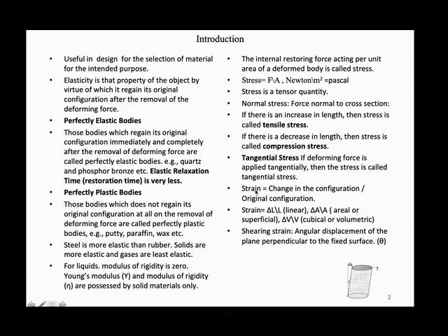So what is strain? Strain is defined as the change in configuration divided by the original configuration. It can be a change of length, a change of area, or a change of volume. If I apply pressure, the volume gets reduced. If I reduce the pressure, volume gets increased. So there is a change in volume, like there is a change in area, a change in length. This is the strain: change in configuration by original. If it is change in length by original length, we call it linear strain. It is areal strain, delta A by A, and it is volumetric strain or cubical strain.